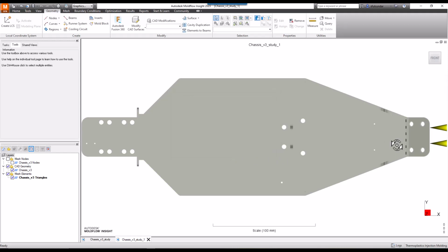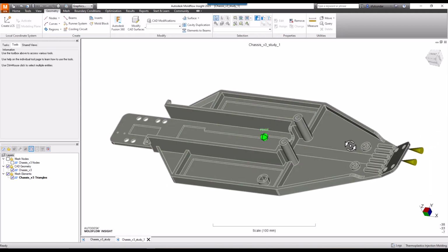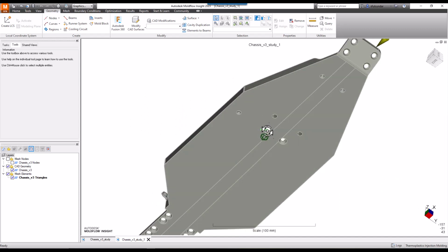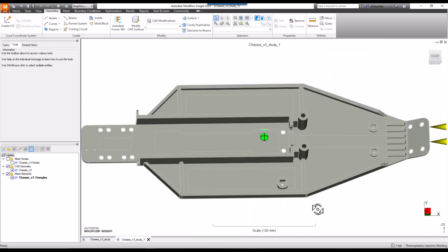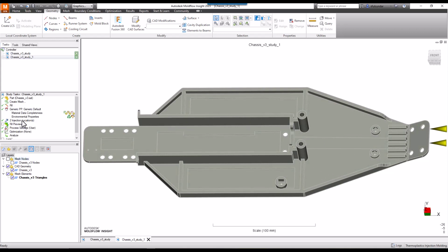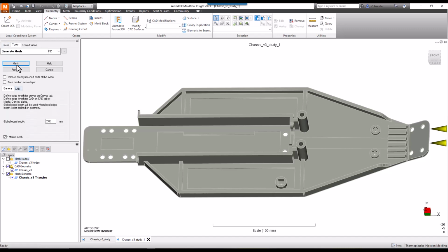There is no change in the gate location, but you can see the geometry that has been updated now has split faces. So let's see whether the mesh that would be created will have aligned elements over here. I'm going to quickly create a dual domain mesh and see if it can create.